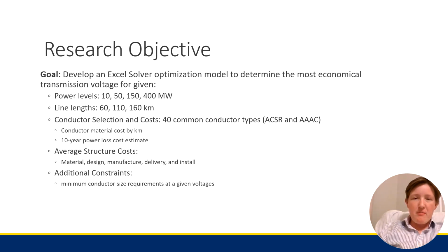So with that background in mind, my research objective was to develop an Excel solver optimization model to determine the most economical transmission voltage. The goal was to take into account the resistive losses from heat, but also the cost impact to building this transmission line model.